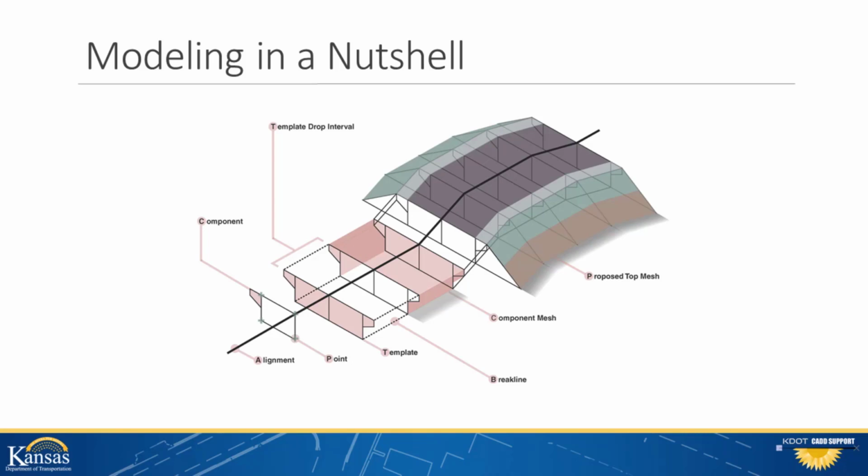The component meshes are 3D elements that allow for very precise volumetric quantities reporting and are preferred over the traditional average end area calculations from legacy applications and workflows. Now let's jump into OpenRoads and look at this more closely.